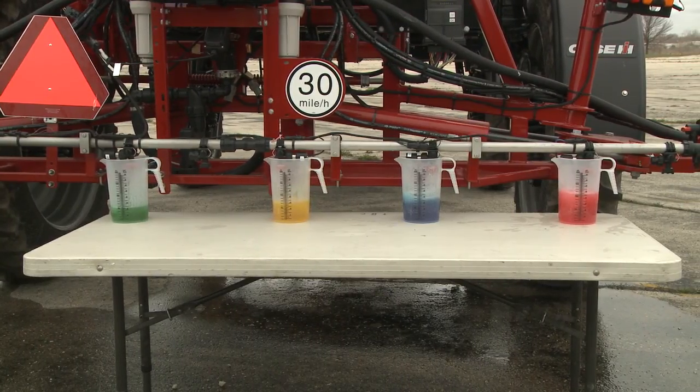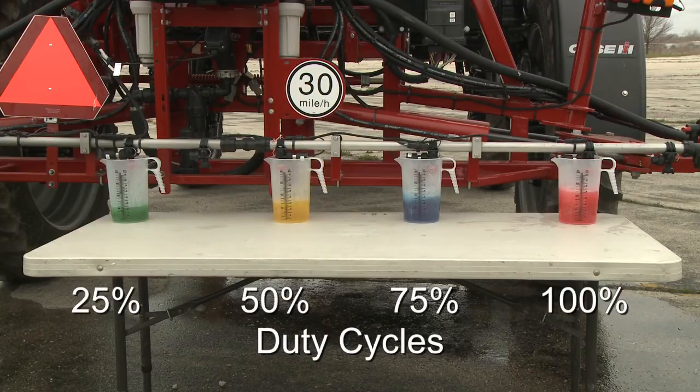The nozzle valves pulse at 10 times per second or 10 Hertz. This cannot be changed. However, the duty cycle can be manipulated to allow flow through the nozzle valve for longer or shorter periods of time, each tenth of a second. This change in the length of time product is allowed to flow through the nozzle is how rate is controlled. This shows various duty cycles and its effect on flow.